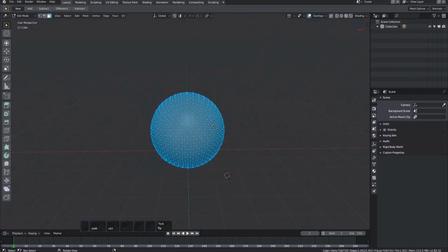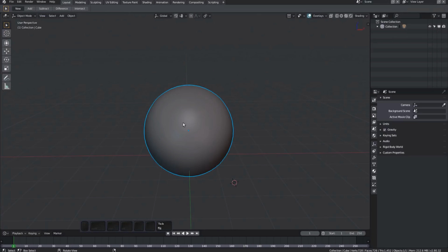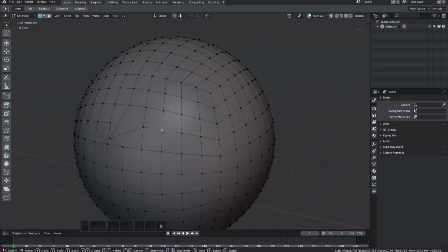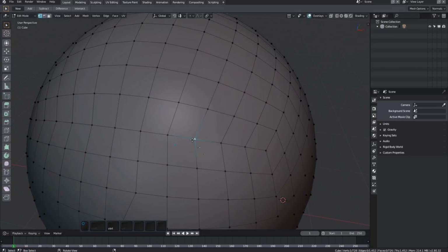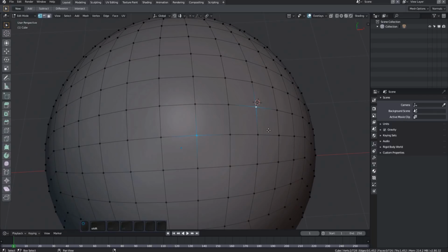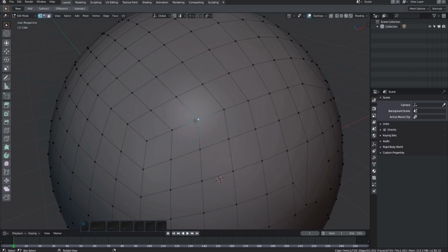Finally, there is one more tool built into Smart Vert. In earlier versions it was called Slide Extend. It can be used to slide a vertex, along an implicit edge, between any 2 vertices, using the Shift-Alt-1 key combination. This can be useful to avoid having to slide on existing edges multiple times. Usually you would use it with the diagonally opposite vert, to maintain the face flatness, but it can be used arbitrarily.